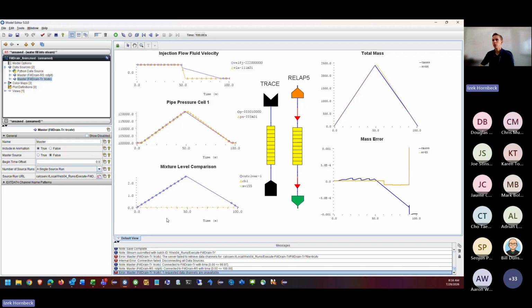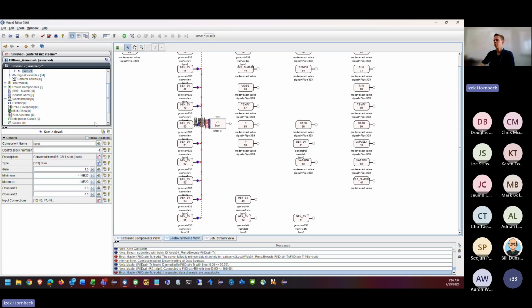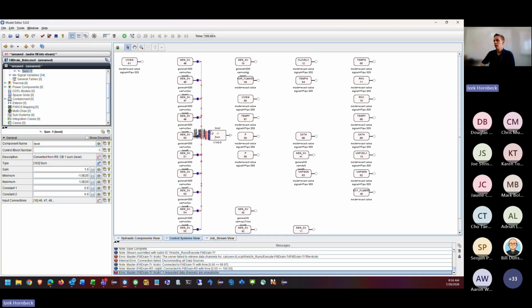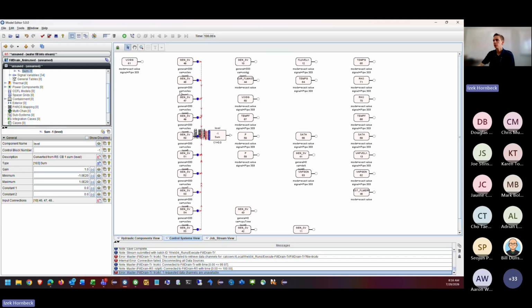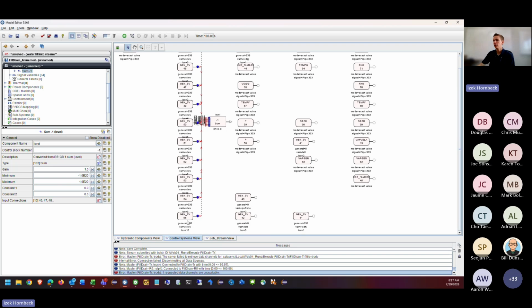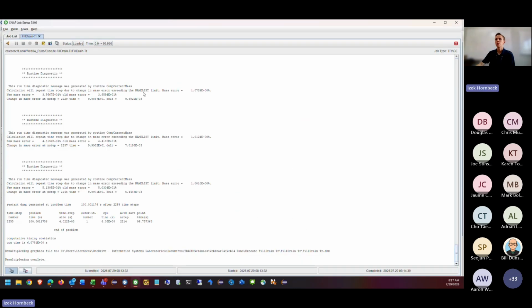So we need to figure out what that is and why it's doing that. If we come back to TRACE, this sum is summing to 0, so we could look at these signal variables right here, signal variables 46 through 55. If we open up our job stream tab again, we can just plot this directly from here, make it a little simpler. So plot with our demultiplexed data here.